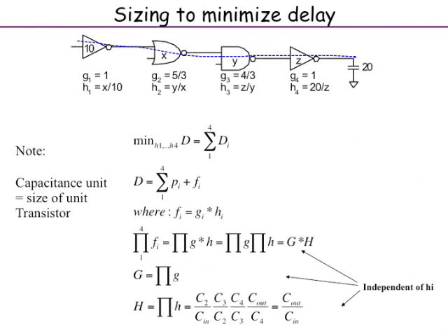These approaches become very important when your delay model becomes more complex, where you start putting in a more complex model for the delay. Maybe I want to consider the edge rate, and so on. Then an analytical solution can become difficult, and at that time this simple-minded approach can help. Of course, you can also apply more sophisticated optimization techniques, which are all numerical techniques.